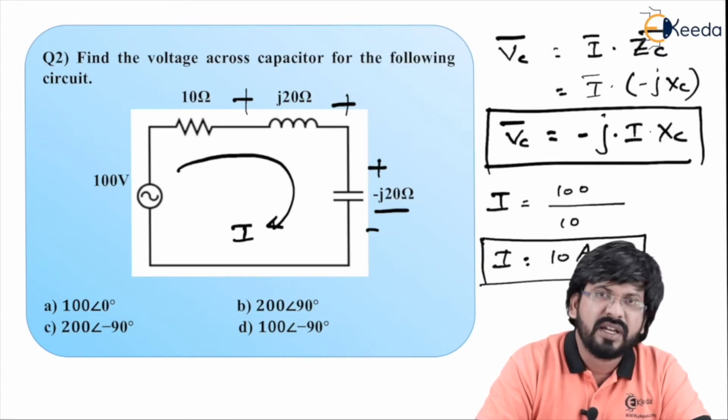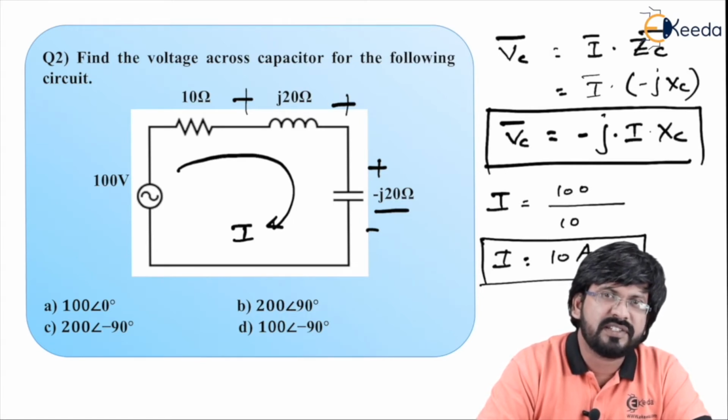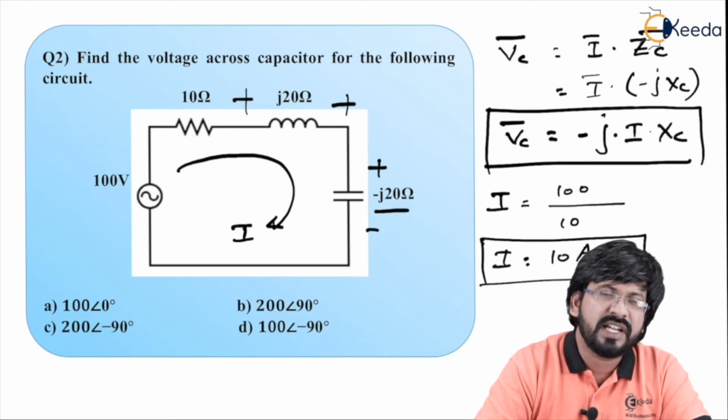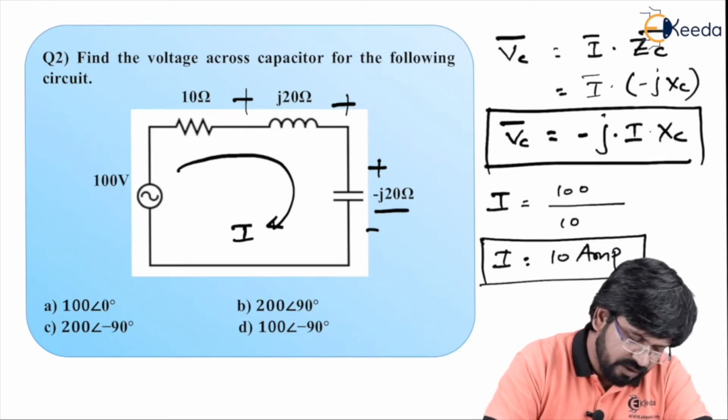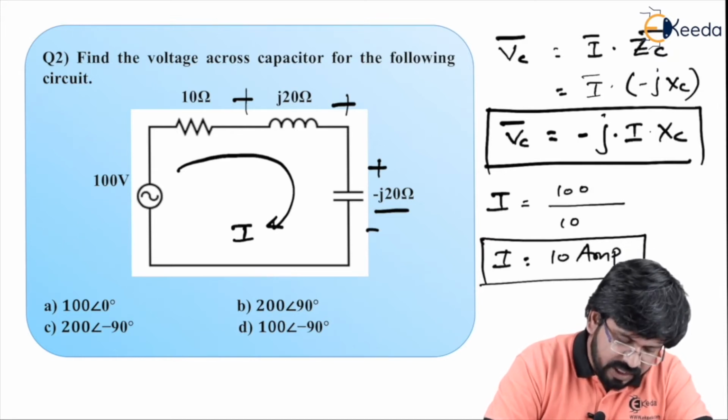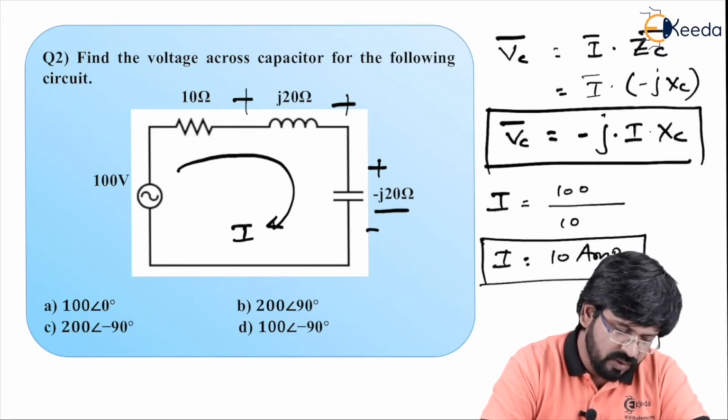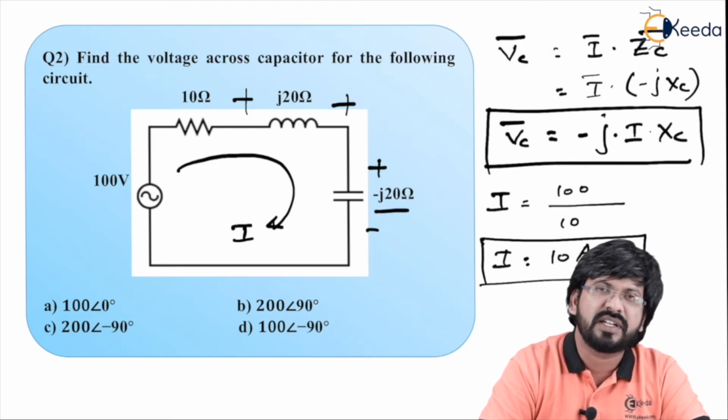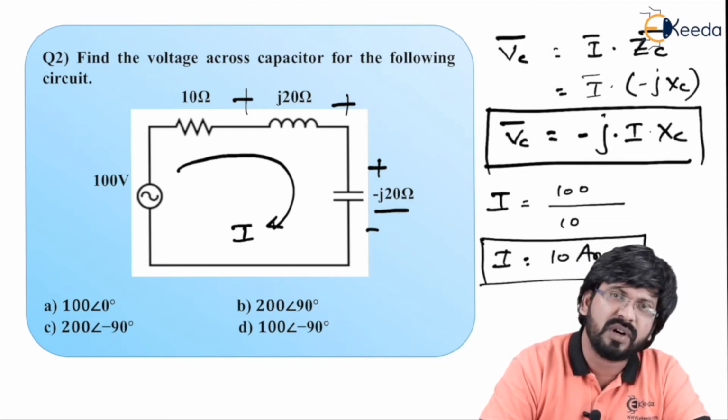In fact, if you can see here, XL value is matching with XC value. It means it is nothing but a series resonance circuit. In series resonance, the circuit becomes a resistive circuit. In a way, assume as if inductor and capacitor are not present, only 100 ohms and 10 ohms resistance is present. In effect, you will always get current equal to how much? 10 ampere.